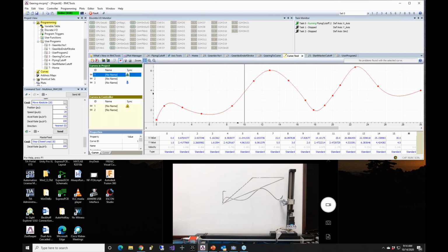So let's say I have these points here, and I'm assuming you want to know the target velocity and acceleration before you actually issue it. We've got these 2 icons here, show/hide velocity, and so you can actually see what velocity is going to be generated from these points. And then also you can see the acceleration profile that's going to be generated from these points. So you can tell what's going on and know if these velocities and accelerations are going to be okay, or if you need to tweak your points.